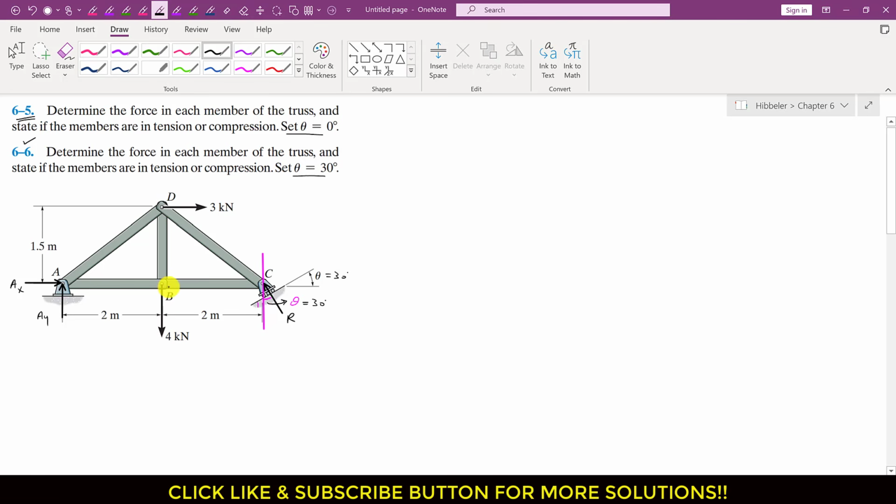Again, we cannot start from this joint B, since at this joint B we have again three unknowns and one known. We need to start from a joint where we have at least one known force and two unknown forces, since we have two equations: the summation of forces along x equals 0 and the summation of forces along y equals 0. So we cannot start with joint D or joint B. Either we start from joint A or from joint C. To start from joint A and C, we need to find AX, AY and this reaction force.